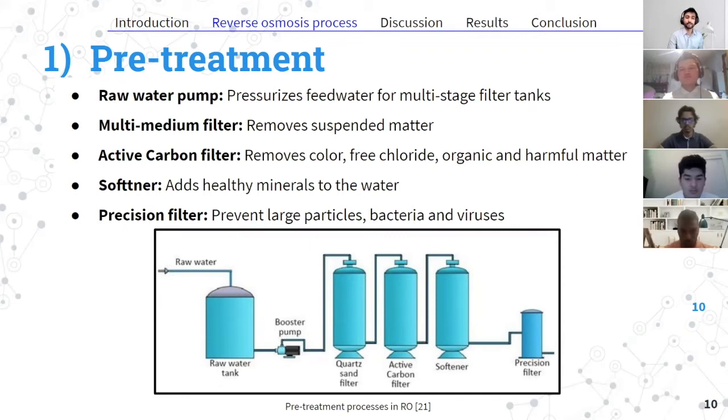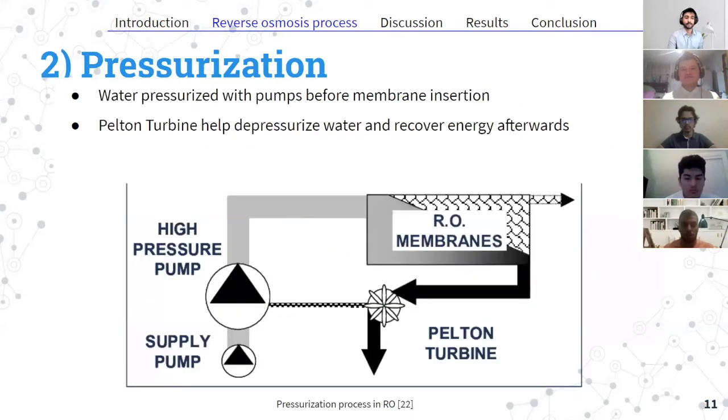An effective pretreatment system can reduce the overall cost and improve the efficiency of the reverse osmosis process, as the separation membranes need to be replaced at fewer intervals. Precision filters before the separation process can save up to 25 to 30% of energy. This all helps to increase the lifespan of reverse osmosis plants.